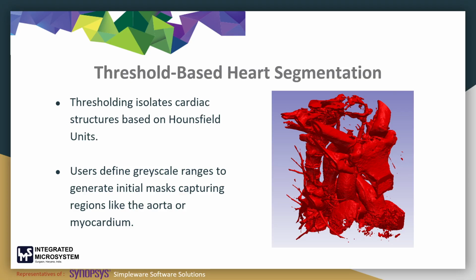What's impressive is that Simpleware allows real-time preview of your threshold mask. As you tweak the values, you immediately see how the segmentation evolves, enabling iterative refinement. This makes it much easier to capture fine structures like platelets, coronary arteries, or even calcium crystals.